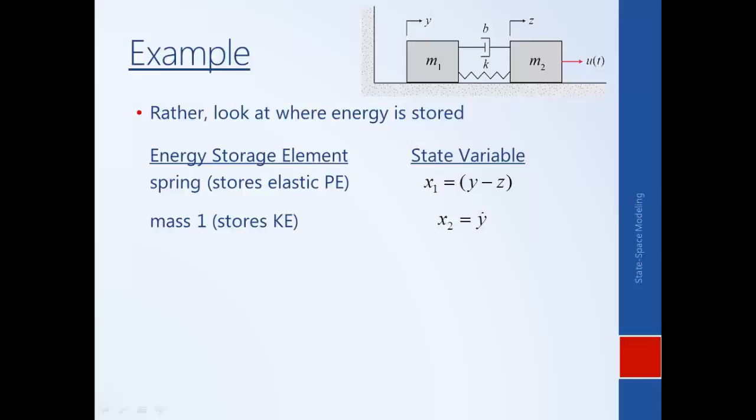It's just like with our motor. A second ago, was the motor at rest and we were applying 0 volts, or a second ago were we applying 100 volts and the motor was going very, very fast? Analogously, mass 2 also stores kinetic energy, where its state variable is its velocity z dot. And so right away we can see that these three state variables capture the state of the system.